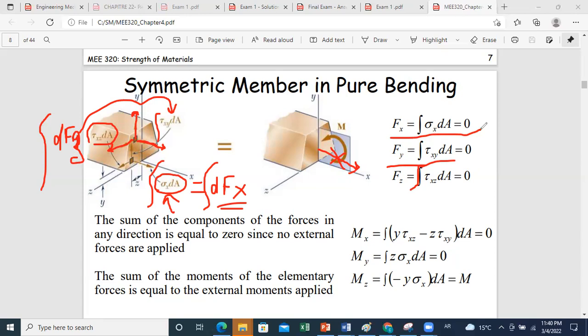Now, this is the force analysis from statics conditions of the support. Now, if we also want to do the sum of moments, we can divide into 3 directions: the moment vector component along x, along y, and along z. Since it's a pure bending problem, you only have in this figure a moment developed along z. There is no moment along x and no moment along y.